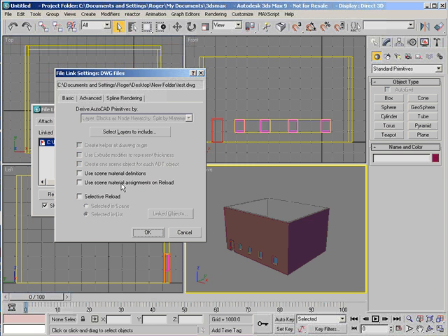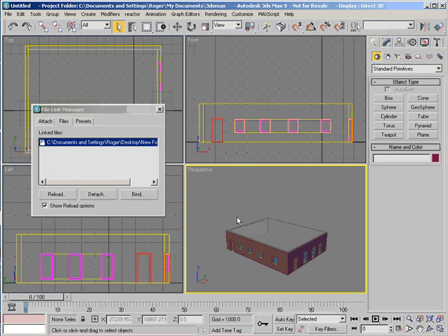If you are importing a scene from Revit and wish to keep all of the material definitions that you have created in Revit, and ignore everything that you do in Max, then you don't select these boxes. But that is normally not the case, because typically you're going to change your materials once you bring them into Max. So you'll want to, when you make reloads, make sure that these two check boxes have been enabled. So we'll click on OK.